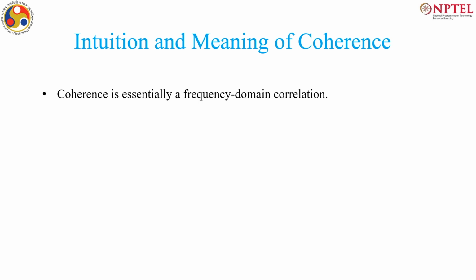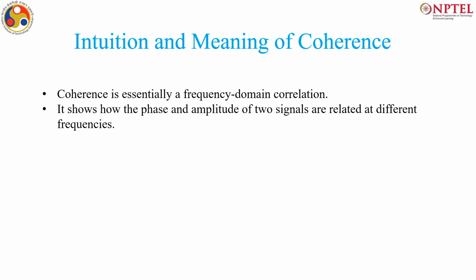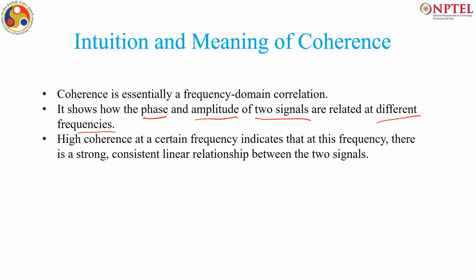This is essentially a frequency domain correlation, and it will show how the phase and amplitude of two signals are related at different frequencies. In correlation we see how they are related in time; this is a relation in frequencies.